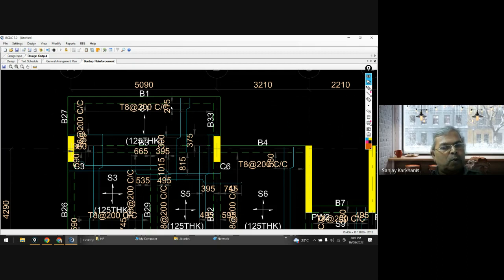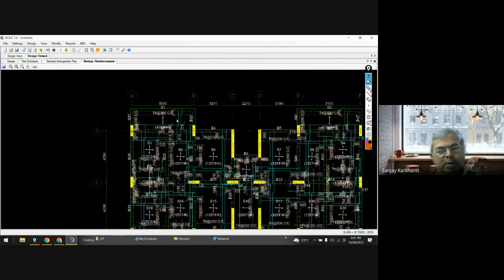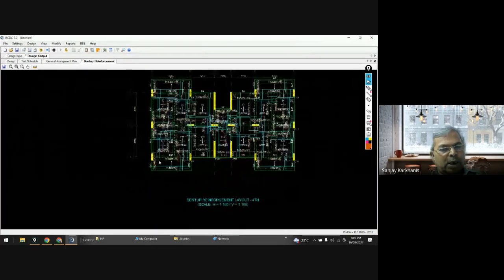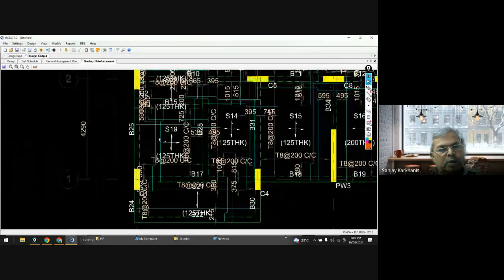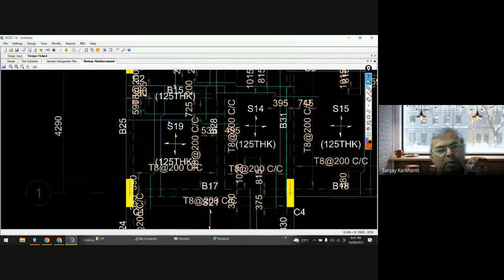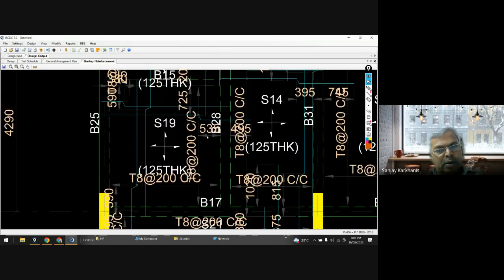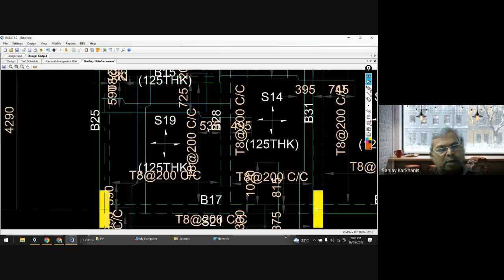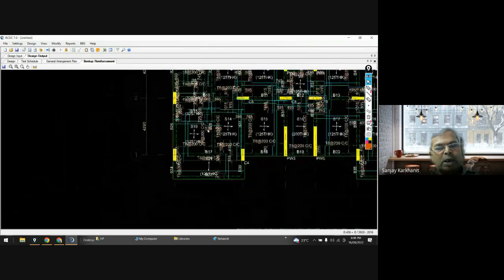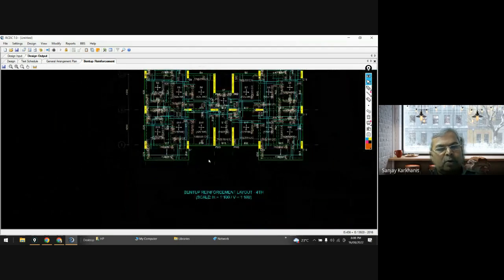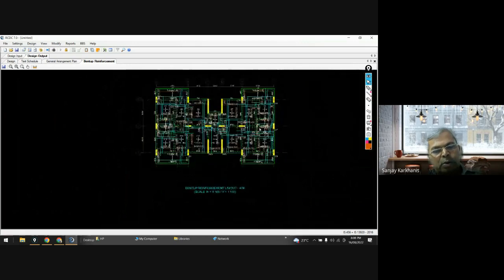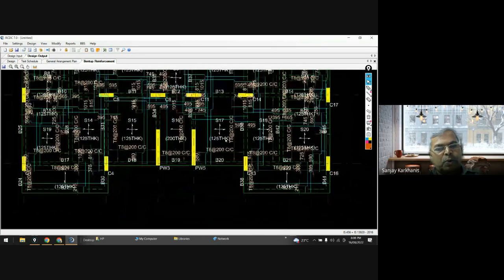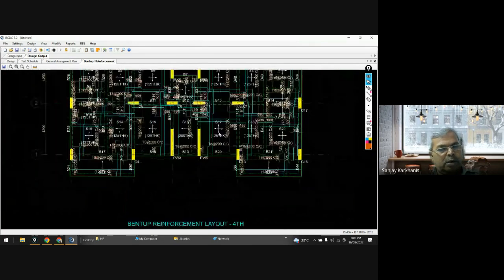So this is about one way. So this is the arrangement. You can see that the bottom reinforcement has been bent and provided on the top. On this side it is L by 4. On this side it has been curtailed at, you can check, it is 530, right? So you can get the general arrangement like this. So bent up schedule. This will give you the arrangement of reinforcement in your slab.